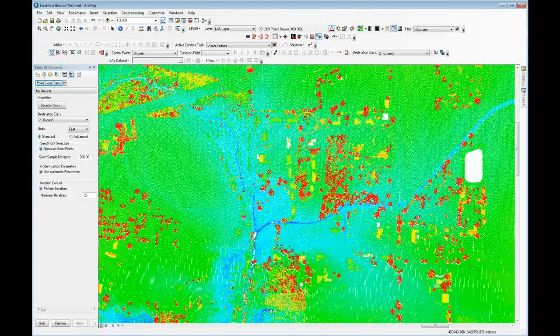But we need to do a little bit of preliminary analysis on the LiDAR data that we're using. So I've loaded some LiDAR data from Escambia County, Florida into ArcGIS, and I'm displaying currently by elevation, not modulated by intensity. So I'm just displaying color-coded based on the elevation. You can see trees, we can see what looks like some water networks.